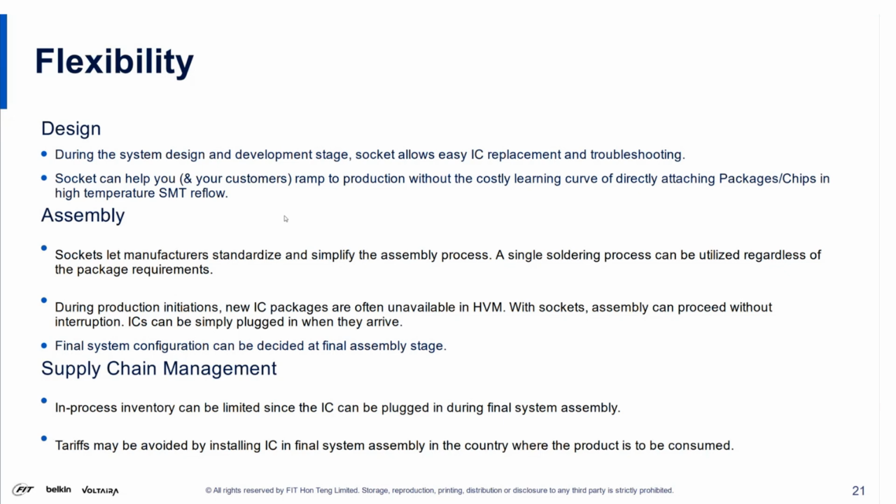The socket can help you and your end customers ramp to production without a costly learning curve of directly attaching packages and chips in high temperature SMT reflow. Like I mentioned in the first bullet, you can do a lot of system level testing and debug without having to work with a direct attached chip. You can do a lot of your design with a replaceable chip.